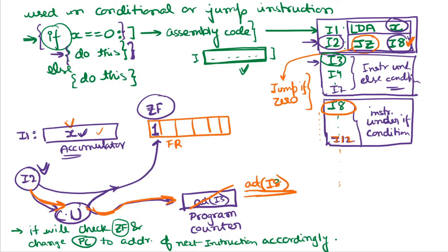Okay, so I hope now you have an idea why this 0 flag is being used, right? So let's proceed with our discussion. Let's discuss the sign flag and overflow flag. Let's start with the sign flag. Before discussing the sign flag, let me tell you that this flag has relevance only when the value stored in the accumulator register is actually a signed integer.